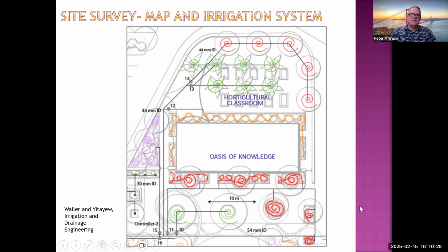And I tried to use the inline tubing in the gardens. I think this was before the small inline tubing, so I was trying to snake it through. But anyway, you can draw your pipe network and your solenoid valves at the beginning of each zone. Notice I've separated different kinds of plants into different pipe solenoid valves. And so that's a nice start, just to start with the landscape architect's design. Unfortunately, this garden was never constructed.